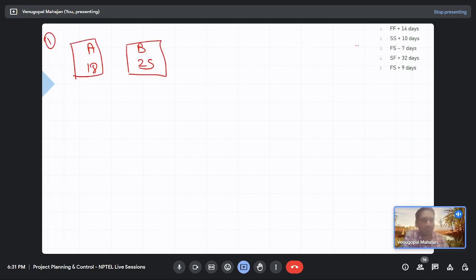What is the first relationship? The first relationship is finish to finish, 14 days, plus 14. So what do you think? What is the earliest start for activity A? I would ask you to follow the steps here. Early start would be 0. Then early finish would be 18.